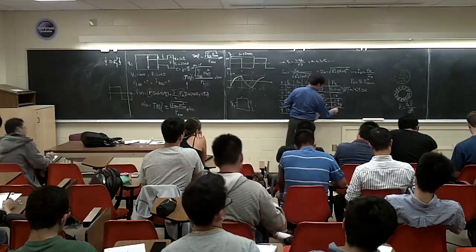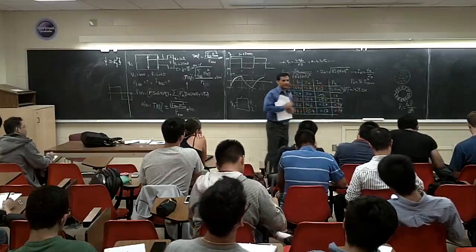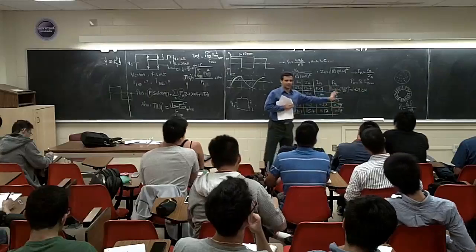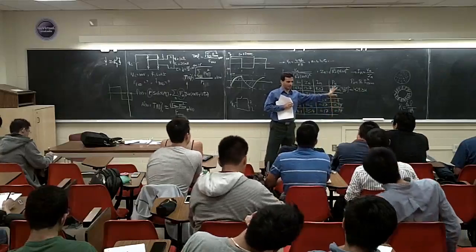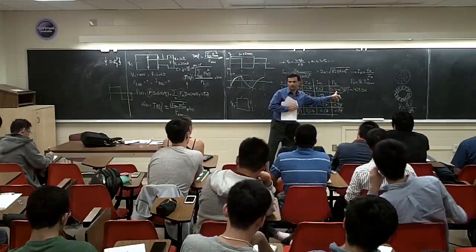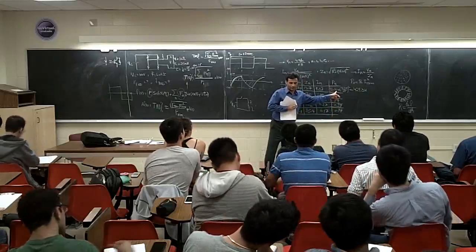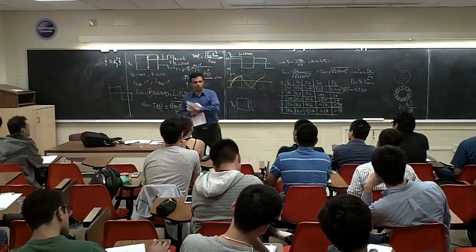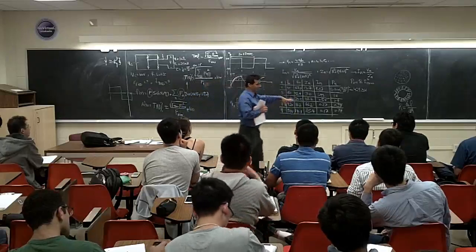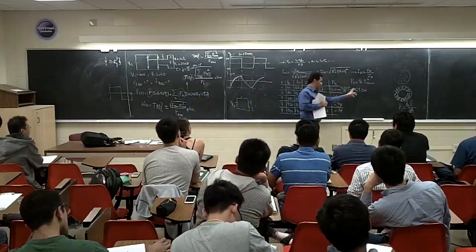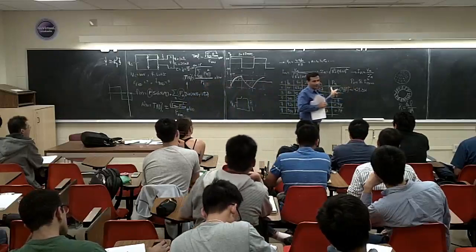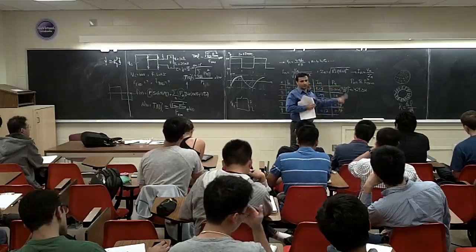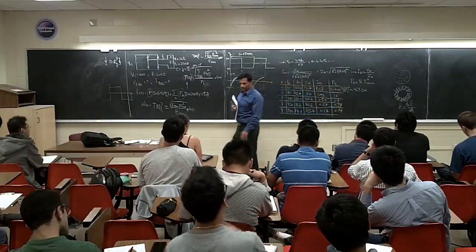This one is going to be 0.14. See? So usually for the power transfer, we don't count these little ones. We say, hey, you're not going to do that much for us. Forget it. We are going to focus on the first harmonic, right? That's what you do. This one takes almost all the power over there. Yes, the others can do some, but this is the one that does more than 98%, 99% of the work. So basically, we ignore the others. They don't transfer any power.